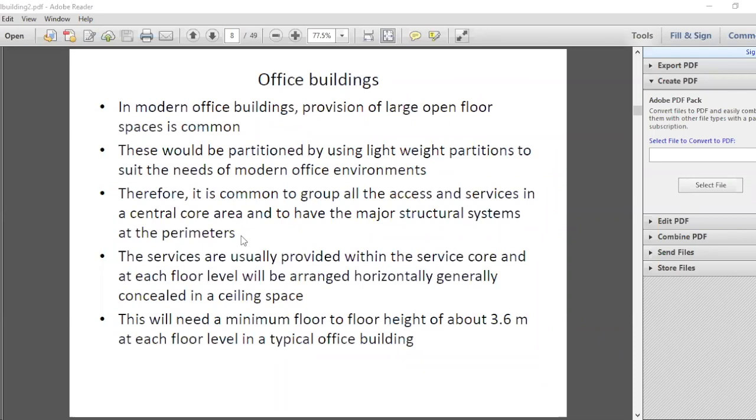In some countries, flat slab is the preferred mode of construction. The reason is the flat slabs can be constructed more easily than the beam slab construction because everything is flat. But the problem is at locations like washrooms, you have to drop the slab. So if it can be accommodated, then flat slab can be a suitable solution.